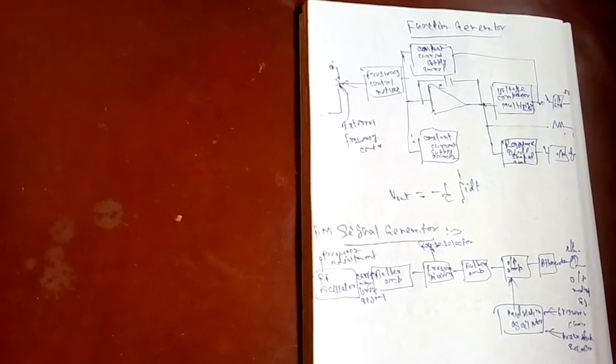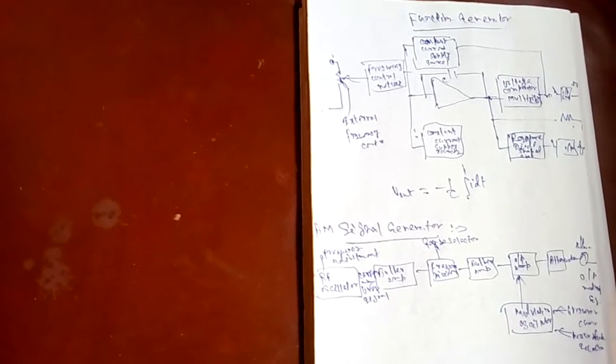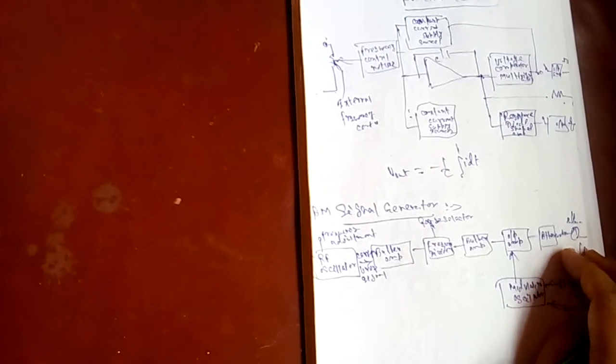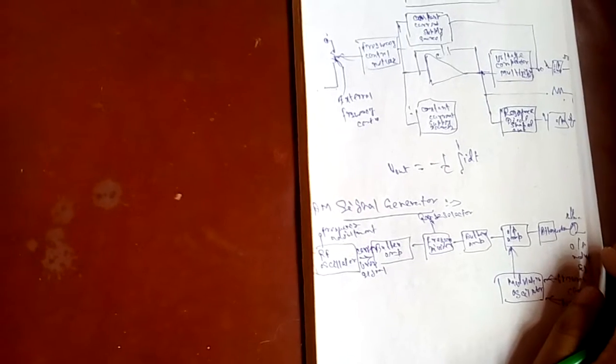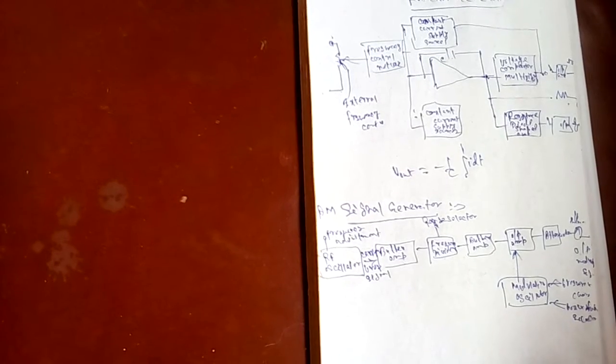The percentage of modulation can be adjusted by the meter, which we see here for adjustment, and the modulation level can be up to 95% of the control device. The output of the amplifier and the attenuator finally go to the output of the signal generator. The output meter is read from the output signal. Attenuators are employed. Why do we use an attenuator? Attenuators are used for a signal generator capable of adjusting the output voltage level from 1 microvolt to 2.1 volt, a range in excess of 100 dB.